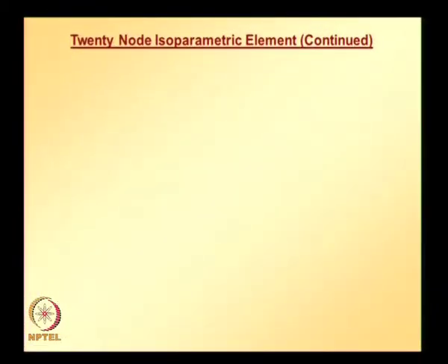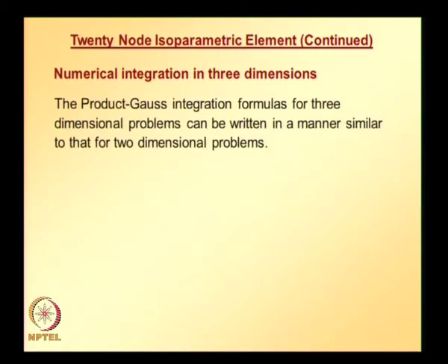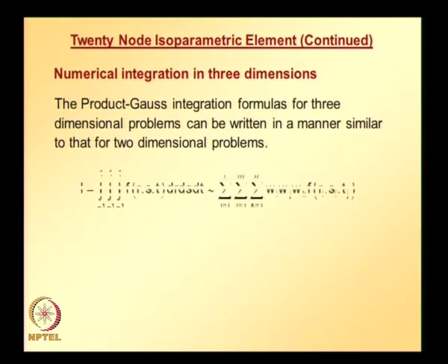Next is the equivalent nodal force vector, but before we proceed there, numerical integration. The previous element stiffness matrix we need to evaluate using numerical integration. So, quickly let us go through numerical integration in 3 dimensions, similar to what we already looked at for the 8 node hexahedral element.